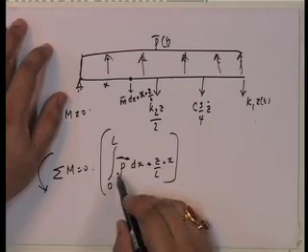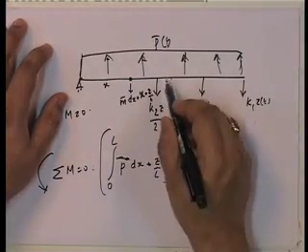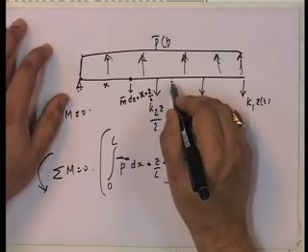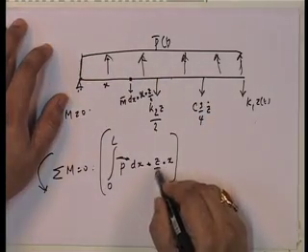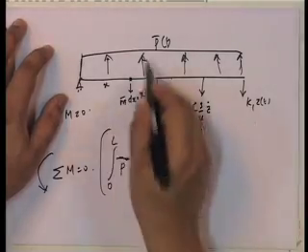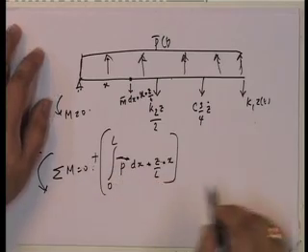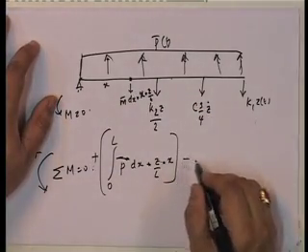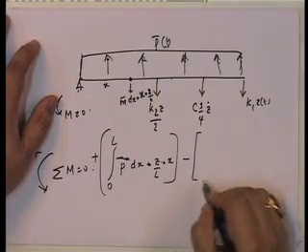And what is this? P bar dx is an infinitesimal length, and the moment by that infinitesimal load P bar x dx is going to be equal to x into z by L, that is the moment, and that moment is anticlockwise positive. So, this is plus. Then I have this moment, this is going to be minus, because this gives rise to clockwise. Let us look at what I have here.